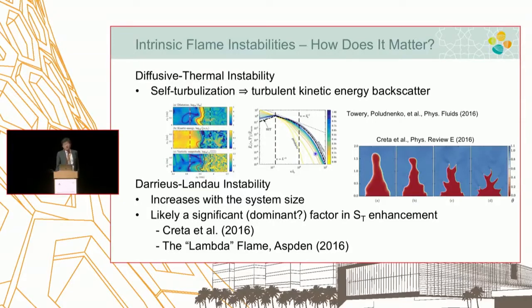In terms of combustion modeling aspects, this Lewis number effect is a preferential diffusion, and the general understanding is that the effect will vanish because the Lewis number determines the laminar transport, but as turbulent mixing dominates in all the flame dynamics, that effect will be overshadowed by turbulent fluctuation. So that's the general qualitative expectation, but there are exceptions.